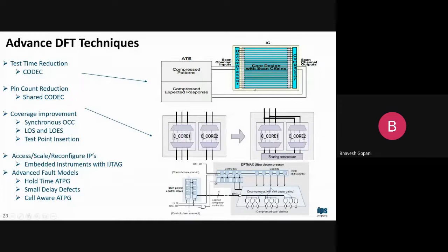So those will be targeted next time. In one pattern, let's say only these 3 chains are excited, and in the next pattern another three, like that. So I can control the power as well. Even here a serializer is used, so I can get multiple inputs from the data, which again feed the decompressor.